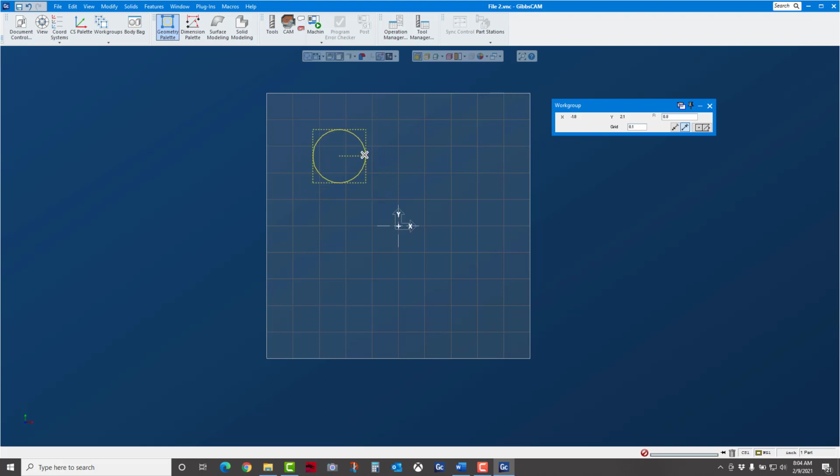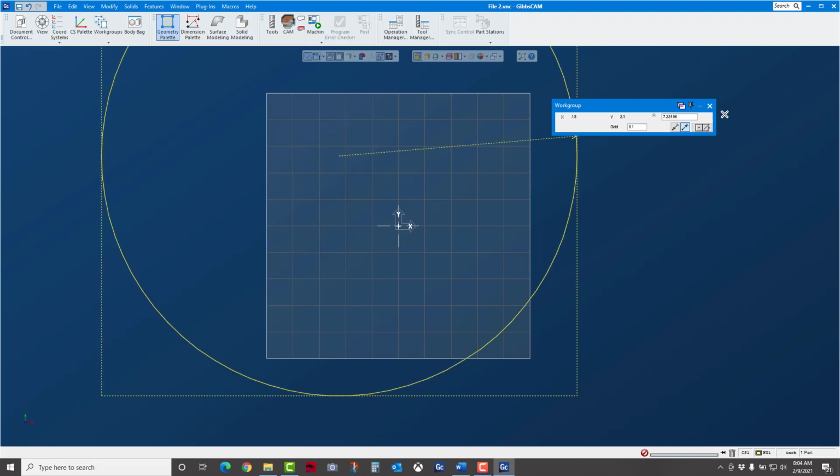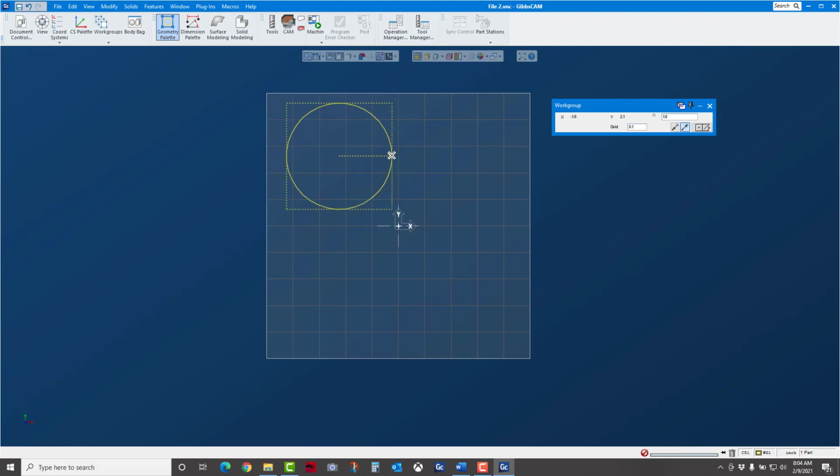Now you'll notice that over in the radius field it's growing by 100 thou because I have a snap grid of 100. If I go to any angle other than the 0, 90, 180, or 270 quadrants, in this case it's doing 4 and 5 place dimensions. So ideally, if you want to size it easily, drag it on the quadrants and then just click, is all there is to it. Now the first one I did anchored from center.